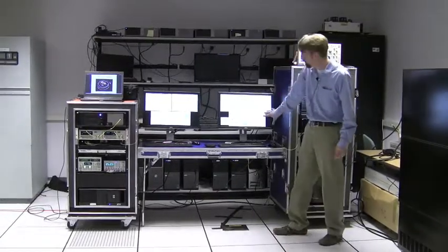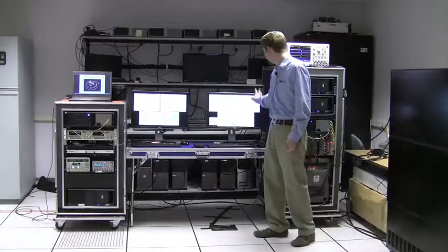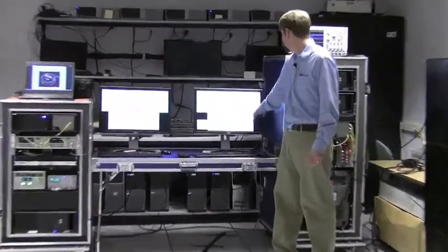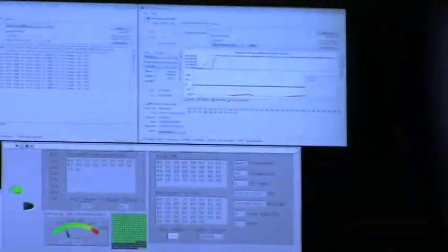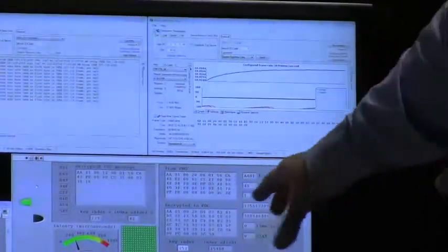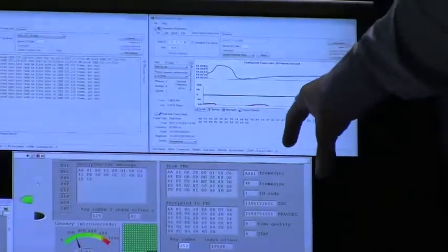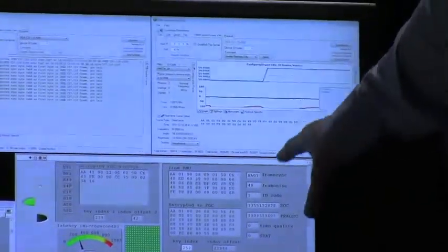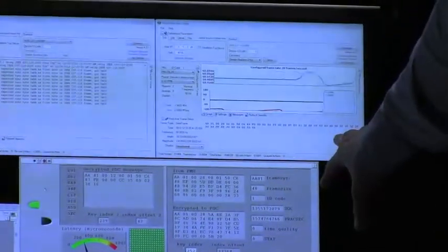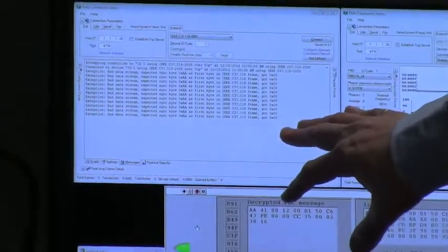So here on screen you'll be able to see some things that indicate that this is taking place. On this computer we have 2 running versions of PMU Connection Tester. This is a program that reads data from the PMU and displays it on screen. You'll see in this window we have PMU data from the TCIPG testbed coming through and it looks good. This is looking at the unencrypted stream prior to encryption and transmission. This window is looking at that exact same data, those very same C37 data frames, after having been encrypted.